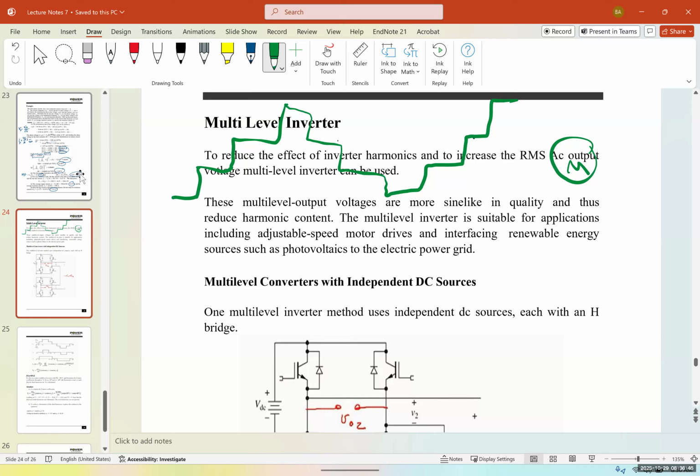Even if the frequency is like 1 hertz off, it must be perfect, synchronized. Voltage must be perfect, the frequency must be perfect. So phase, voltage, frequency, all of them must be, and the shape of the signal, obviously. Creating harmonics is going to heat up the transmission lines. It's going to cause a lot of damage. So for those that need a very clean signal, multi-level is the way to go.